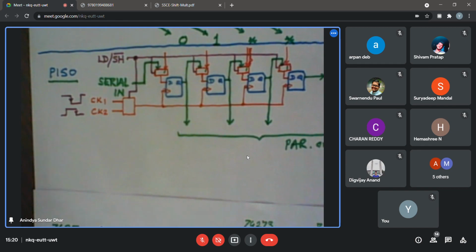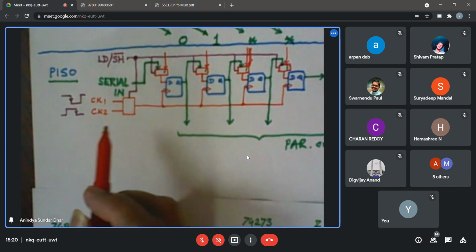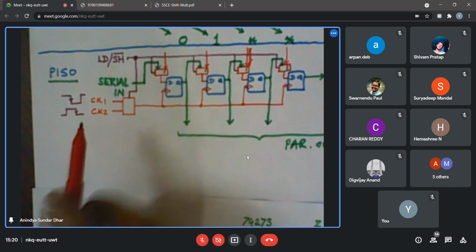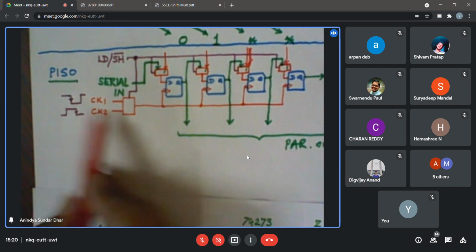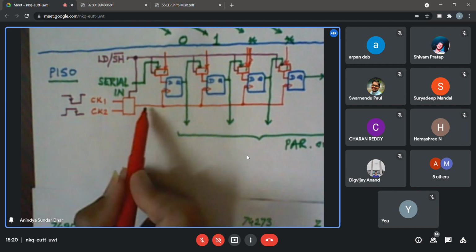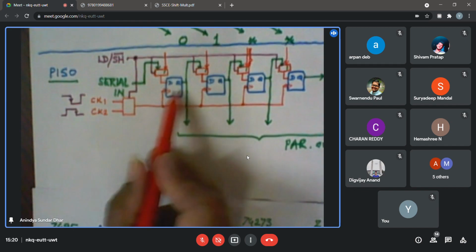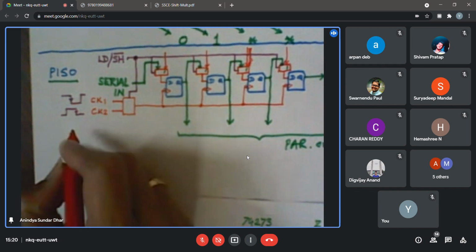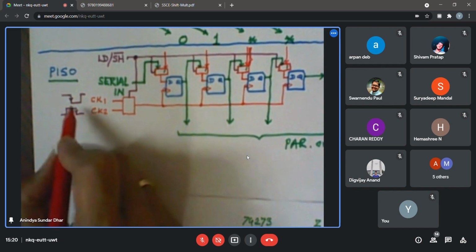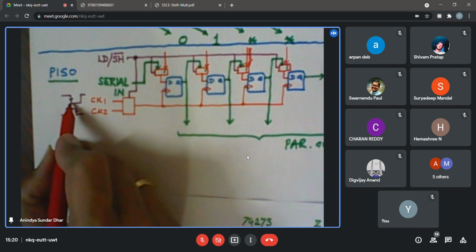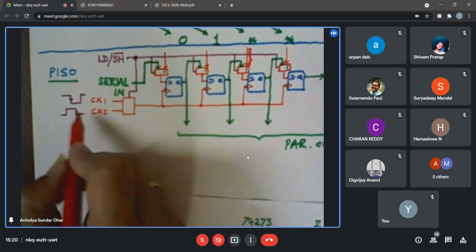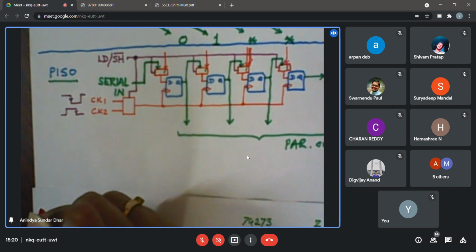Yes. So when you shift, let us say from clock 1 to clock 2 or clock 2 to clock 1, what could have happened? Suppose here I am shifting from clock 2 to clock 1. So look at this output, which is actually being given to the clock. Suppose I shift it in between when it is low, and consider the other situation also: I shift it when it is high. So could you guess what might be the problem?